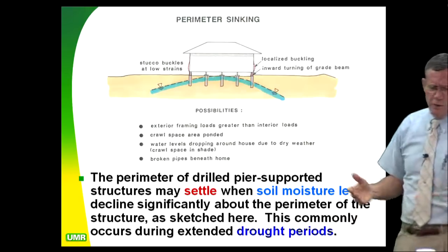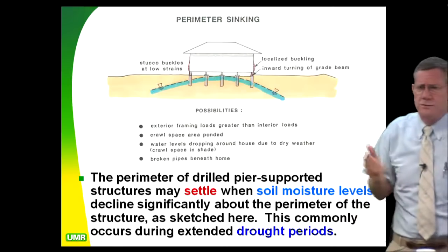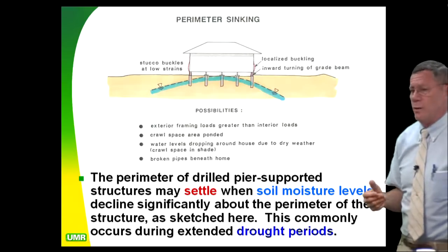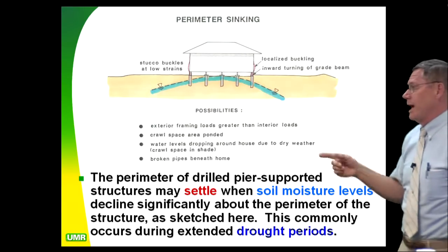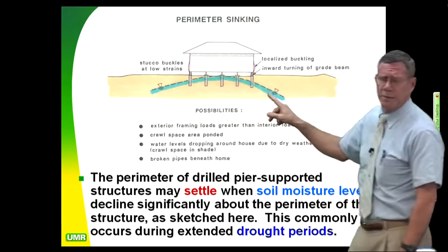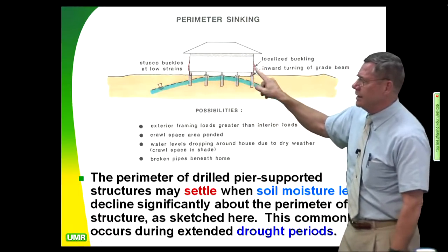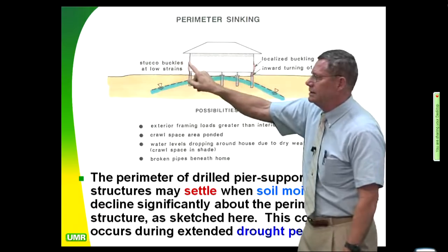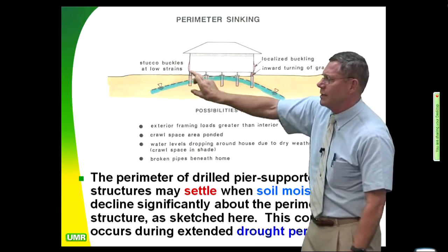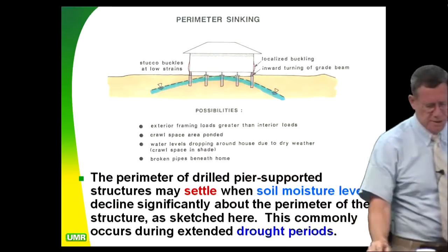So Honolulu Board of Water Supply told everybody, yeah, we're in a water drought situation here. Quit watering your lawns. So people quit watering their lawns, and what happened is they started seeing these kinds of situations where they're getting interior doming, and you'll actually see buckling right here, and buckling of the sheathing right there, because this is dropping on the edges.